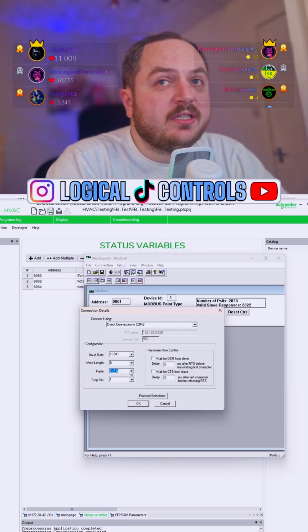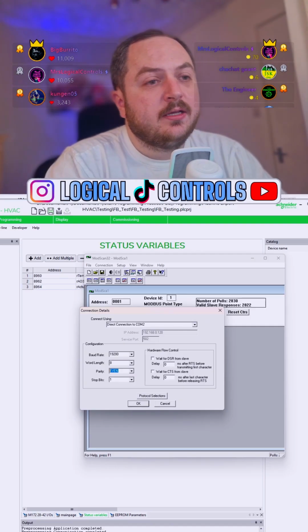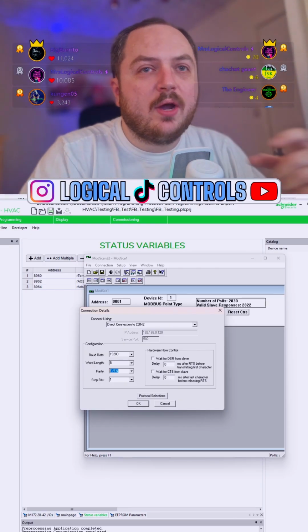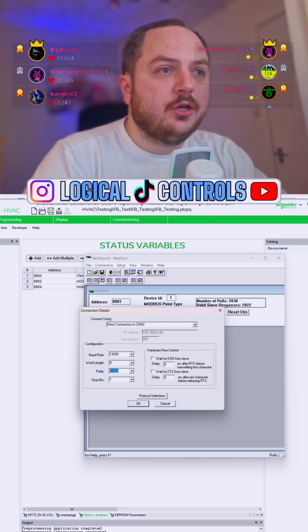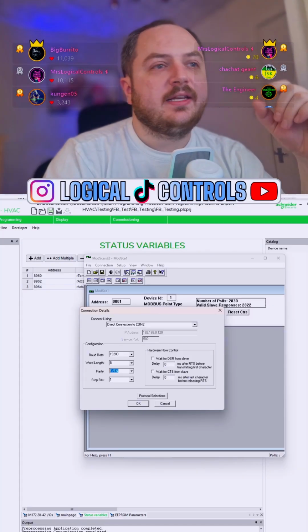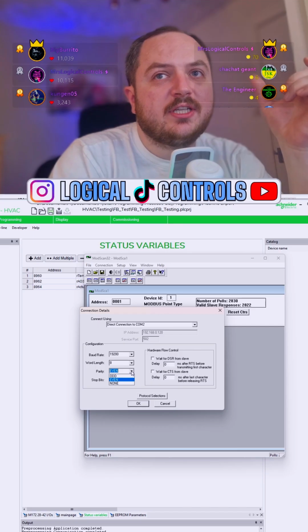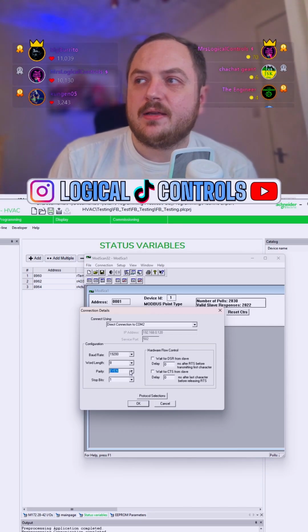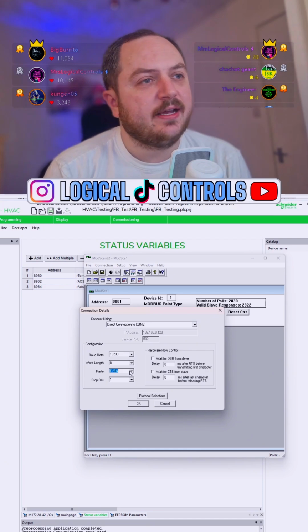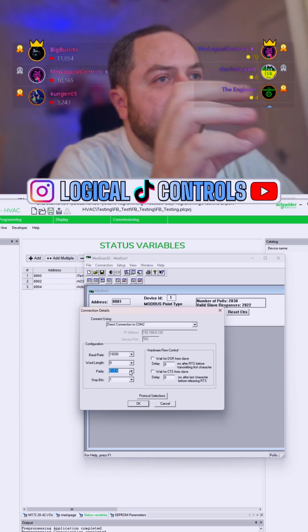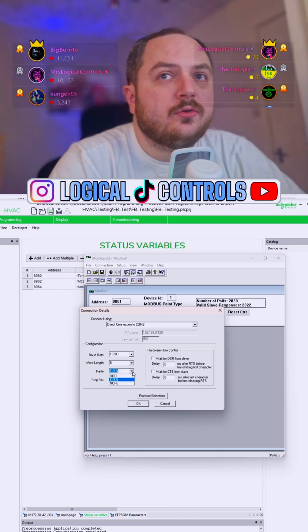You have a parity, so that's basically so when you're sending Modbus requests and when it's returning the data, there's like packets of information and there's standard lengths. So what you're saying here is, should that data message end in 00, basically should it be made up of even numbers or odd numbers?